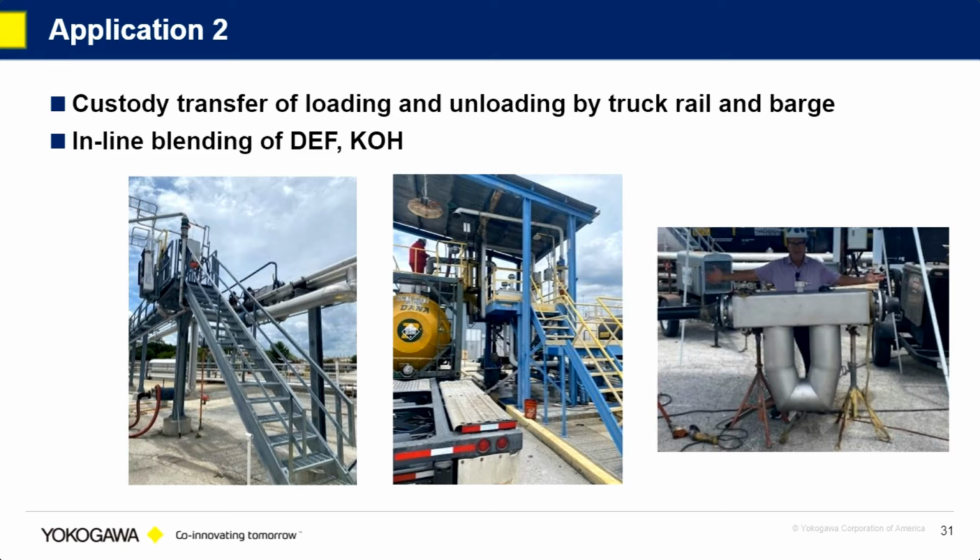So this is a couple pictures of that. We also can do inline blending. Very often people will blend things in a tank. We've done inline blending for diesel enhanced fuel, KOH, just to name a few, HCl, where you're actually blending to a certain concentration directly into a truck for custody reasons.